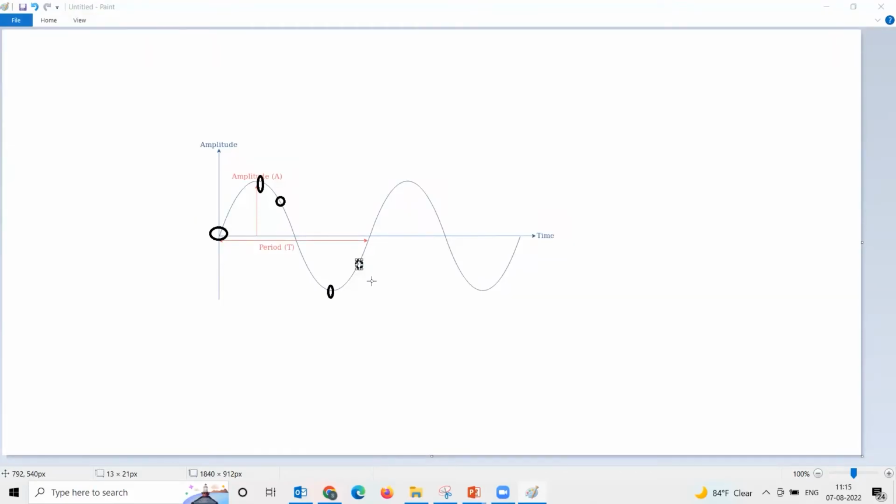The answer is quite simple. Our objective of performing short circuit studies in ETAP is not really to find out what the current is, but instead our objective is to find out what the worst case is. That's as simple as that. We are just looking at the worst case.